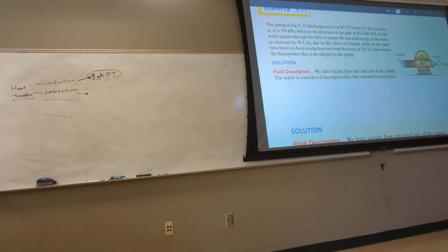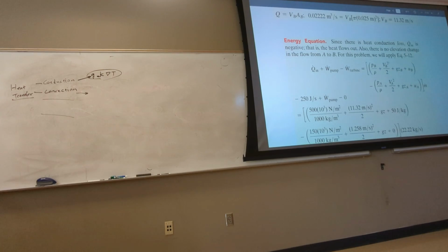So look at here, it makes sense. The inlet you get 1 meter per second, the outlet 11, because why? You got a pump here. The pump will do the work for you to increase the speed, increase the head. Right? So now back to the equation.